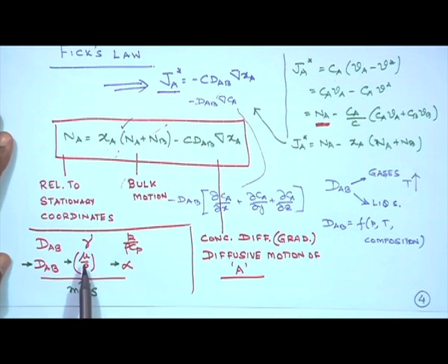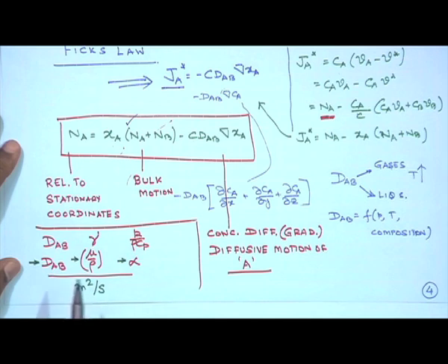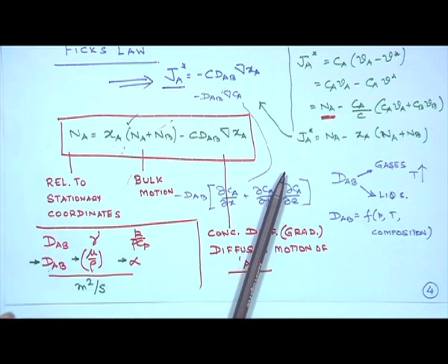The mass diffusivity, the momentum diffusivity, and the thermal diffusivity have the same unit, meter square per second, and all of them denote the transport of mass, the transport of momentum, or the transport of energy when you impose a concentration gradient, a velocity gradient, or a temperature gradient. So, this would be the beginning, the start of the analogy, finding the analogy between different processes: heat transfer, mass transfer, and momentum transfer.